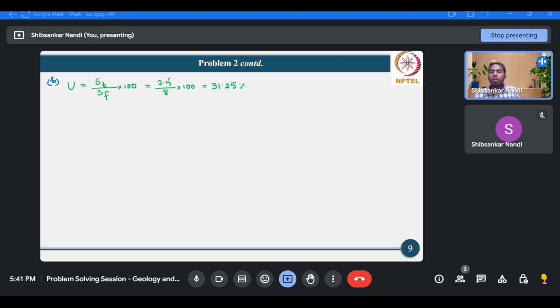Now, once we know the degree of consolidation, we can calculate the TV value from this equation. Okay. Again, it's less than 60. So we'll use the first equation, and the TV value would be 0.077.